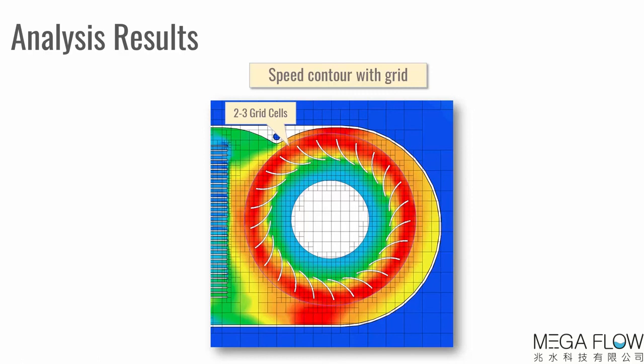Though the grid is coarse, I would like you to notice how well the geometry is resolved, particularly the blades, with the smart cell technique used by Flotherm XT. Even the curvature of the graphics card cover is captured well with no additional grid settings or higher mesh count. This model has about 580,000 grid cells.